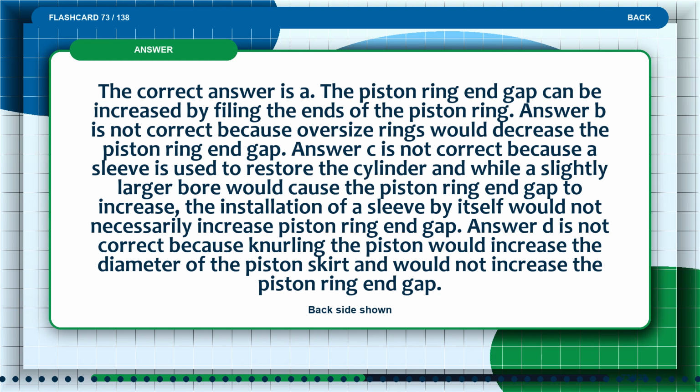The correct answer is A. The piston ring end gap can be increased by filing the ends of the piston ring. Answer B is not correct because oversized rings would decrease the piston ring end gap.